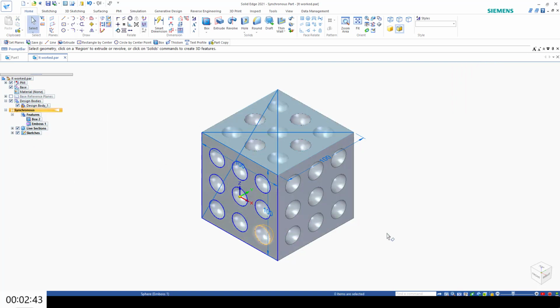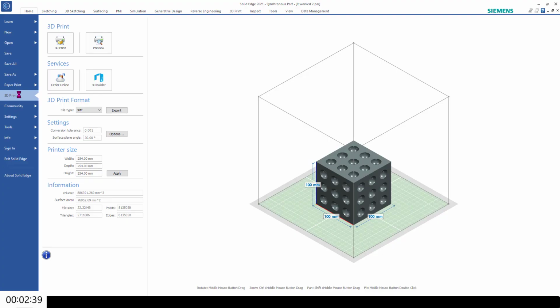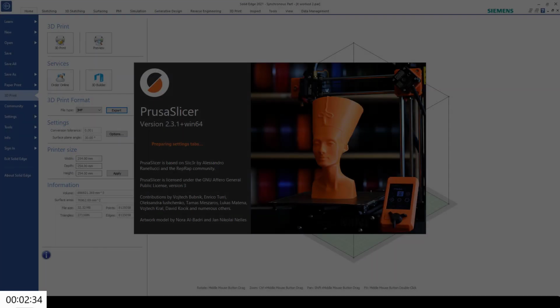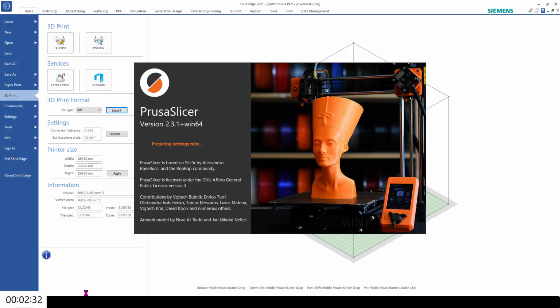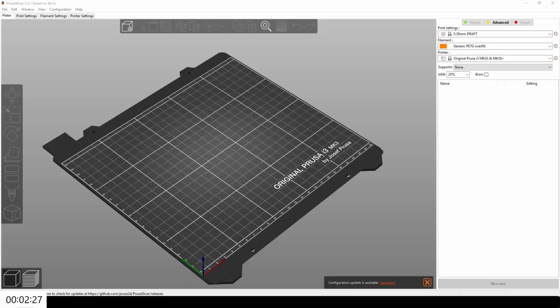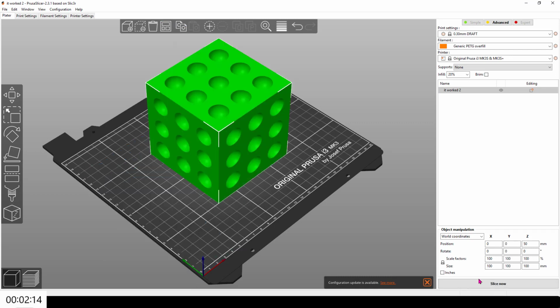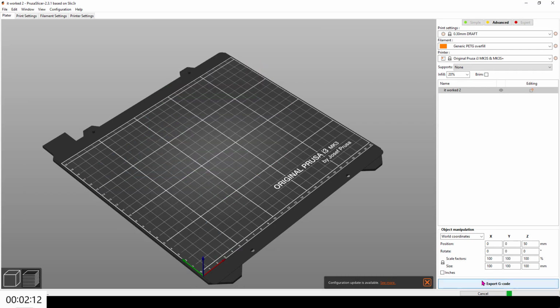All right, so Solid Edge took a really long time to render out to this view, probably because the geometry is fairly complicated. And now I'm going to bring it into a 3D slicing package. So here's my Prusa slicer. And you get to see what this object looks like as it would be made with a 3D printer. So drag and drop it in. It's fairly large and complicated. Slice it up. It's going to take a few moments.